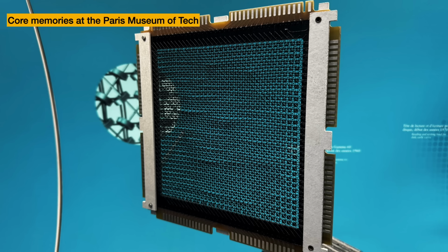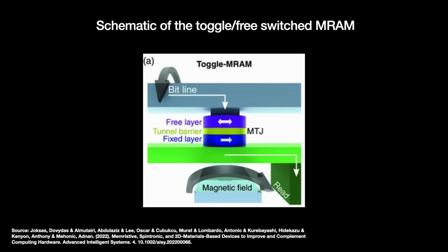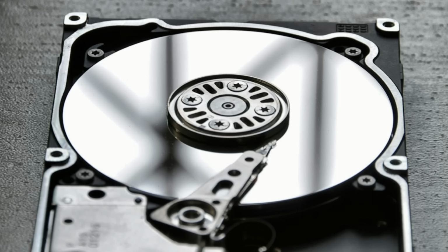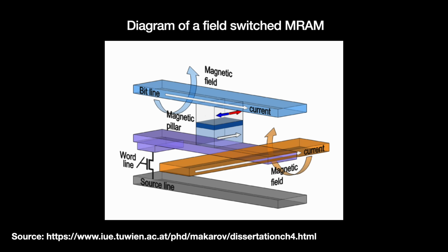For this mechanism to work, the magnetic field has to be strong enough to flip the MTJ's magnetic state. The problem was that as the MTJ got smaller, it gets easier for that bit to accidentally flip due to thermal noise. Hard disk drives suffer this problem too. They have something called the superparamagnetic limit, where the grains in a bit get so small that thermal energy can flip them. Anyway, the response by engineers has been to raise the quote-unquote flip limit.